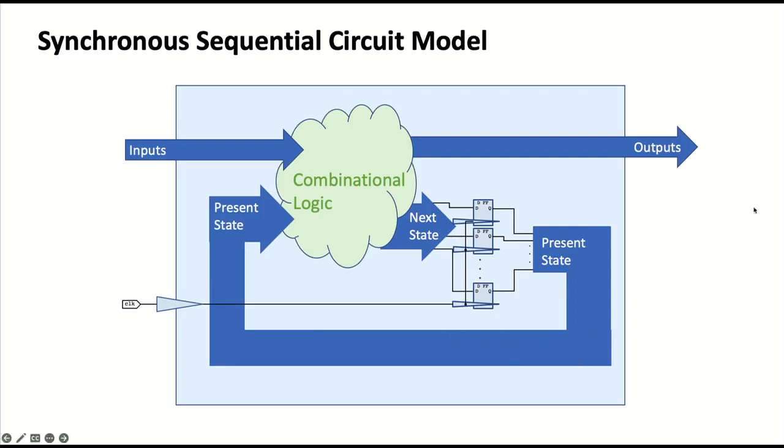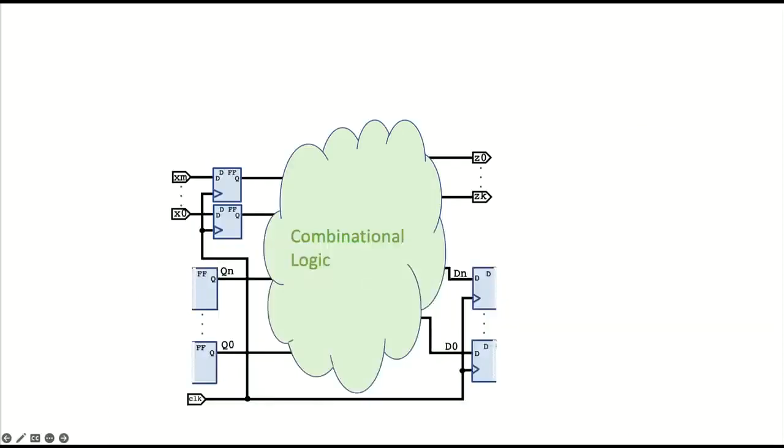All we need to do then is analyze this circuit and figure out what the worst delay is for this circuit, or the smallest delay. If you have a combinational loop, that requires much more analysis, and then timing starts to affect the values that you get and whether it settles at all.